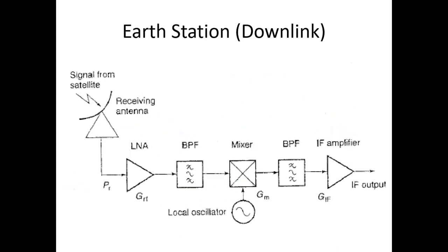No, at the earth station you have a local oscillator we see, and it uses that superheterodyne method for amplification. So an intermediate frequency amplifier, IF amplifier, will work here, which has a narrower bandwidth.